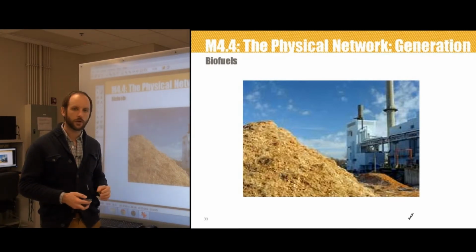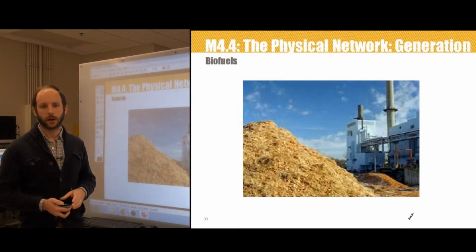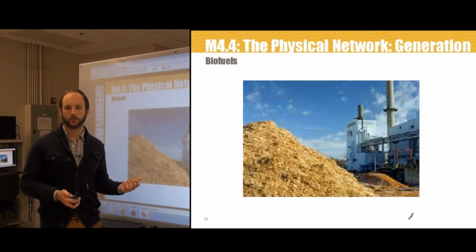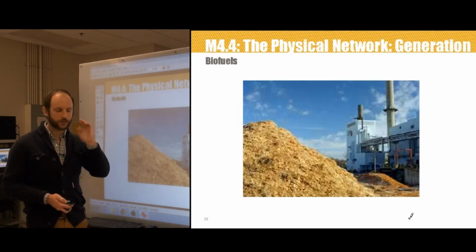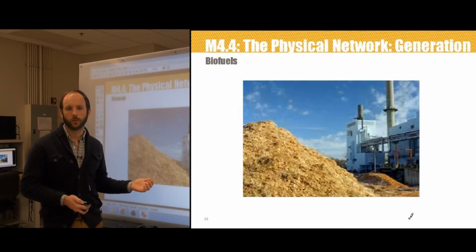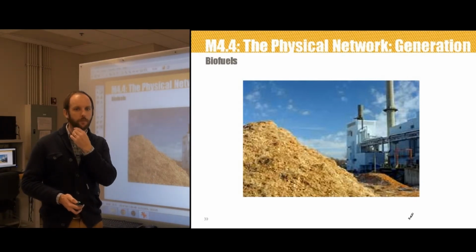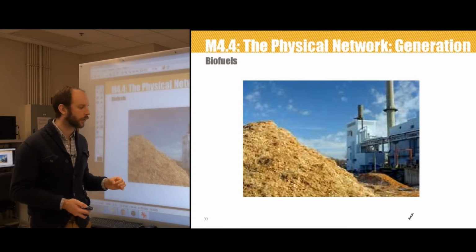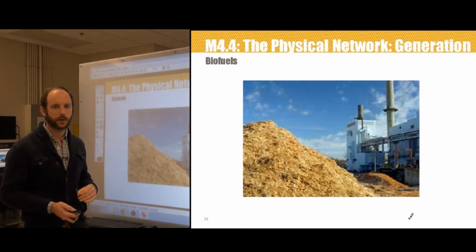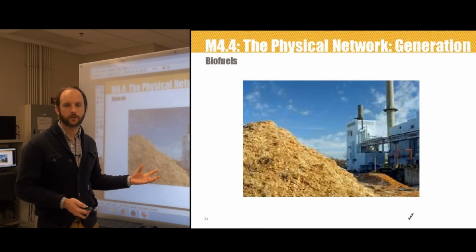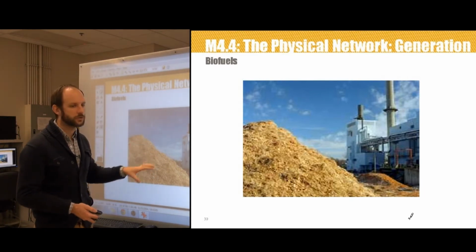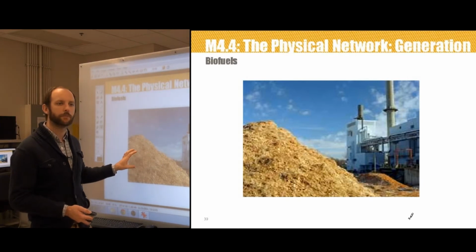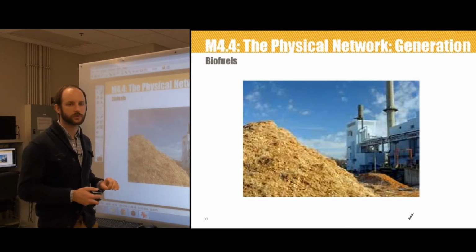So long term, though, you're probably not going to see a major influence of biofuels in the electrical generation market for two major reasons. First of all, using waste biomass is typically a means of ridding agriculture of waste, and is very inexpensive. But this is a world of difference from growing crops specifically to burn in power plants. So large-scale adoption of this, where we actually grow fuels to power power plants, is probably not ever going to be an economical method to produce power. It'll probably just be relegated to situations where we're trying to burn waste products from other situations.